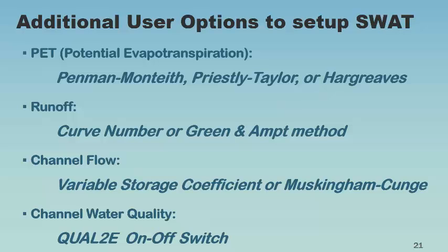So as I was mentioning to you, there are ways in which you can spatially construct your model, like a lumped model or HRU model or a landscape model or a grid model. You can also take each of those spatial models into further process-based models. Actually, here you have options to choose different potential evapotranspiration based on the input of your data. If you have all the weather variables, you can use Penman-Monteith. If you have only temperature, you may want to use only the Hargreaves model, for example. So you can have sub-models within the SWAT model for the various processes and the interactions.